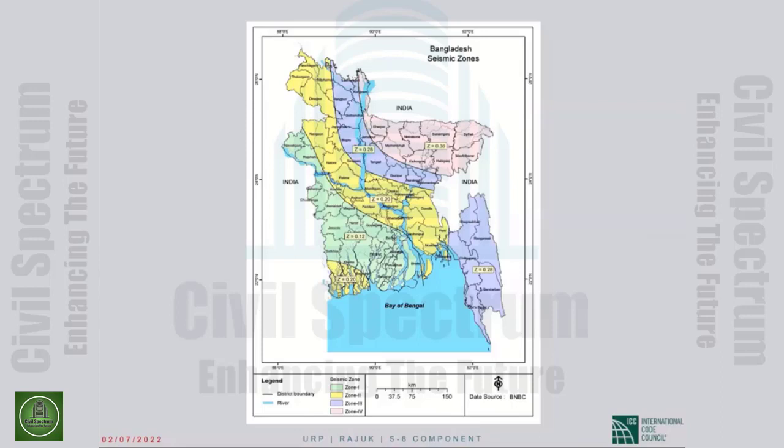Basically, you can increase the stiffness of the building by putting shear walls in wherever there is scope, or you can try to make those columns very ductile after the fact, which is a very expensive solution. And there are other innovative things you can do, but anyway, there are only expensive solutions. So the owner has to be willing to spend the money and engage the right help, and even then, it is not going to be easy.